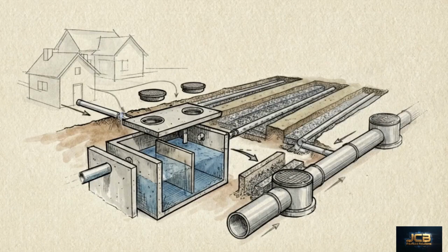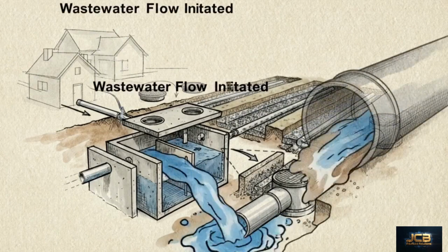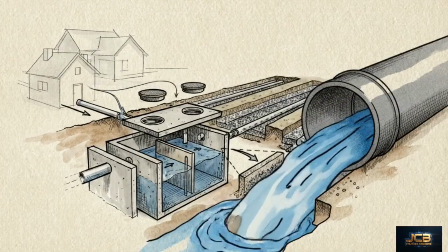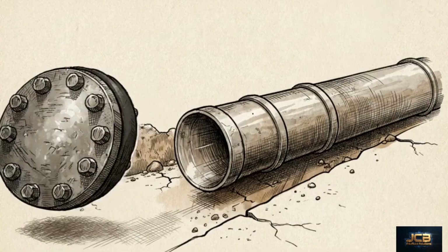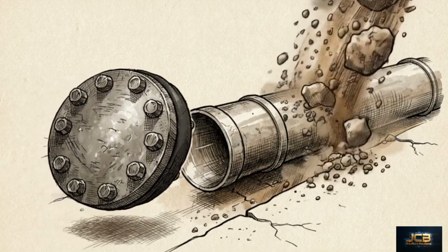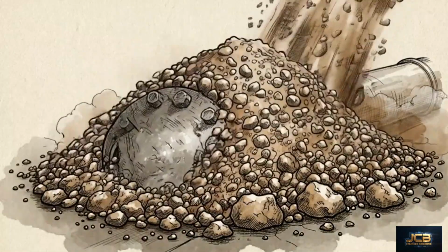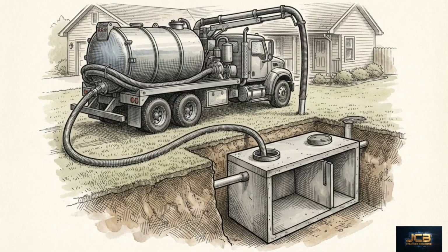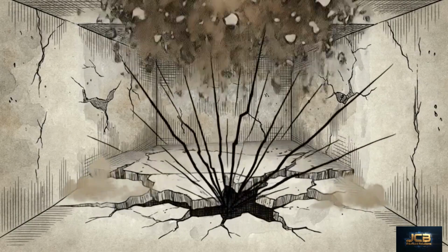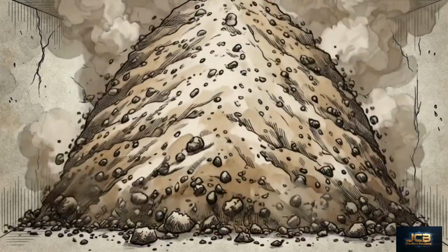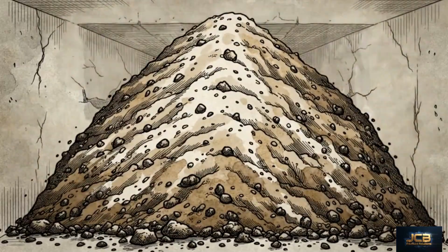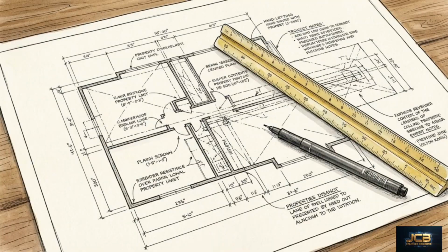When a public sewer line eventually reaches a property, the private system becomes obsolete, triggering mandatory abandonment protocols under the code. First, the existing building sewer that originally fed the private tank must be disconnected, securely plugged or capped within 1.5 meters of the property line. Second, the septic tank or seepage pit must have its contents completely pumped out and properly disposed of. To prevent a subsurface water trap, the structure's bottom must be shattered and the void completely filled with earth, sand, or gravel.